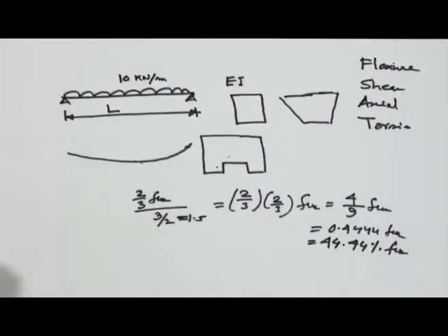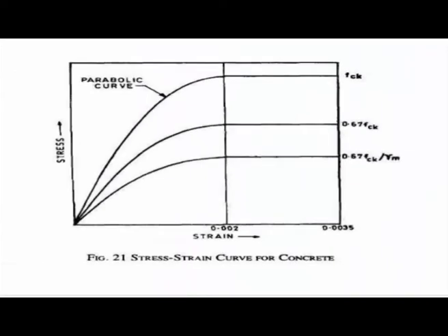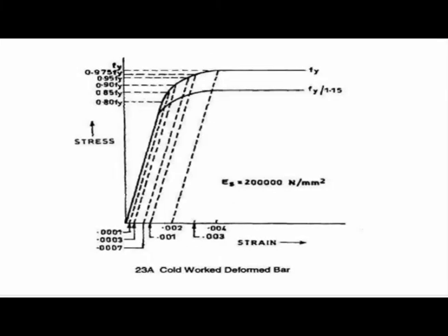So what we are doing is that so far we have covered the beam. Mainly we have two things. One is bending, and the other one is shear. For bending we provide reinforcement like this. For shear we provide reinforcement in this fashion, and we call it shear reinforcement.